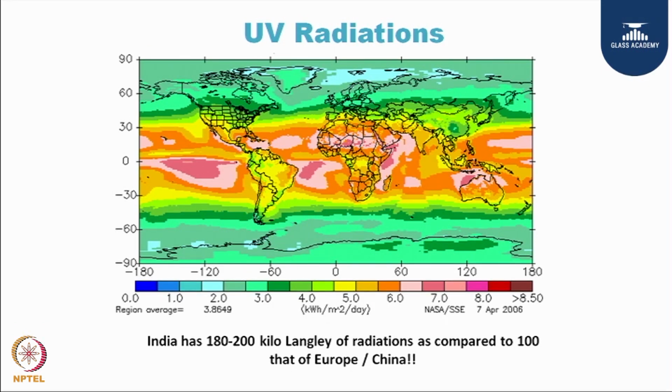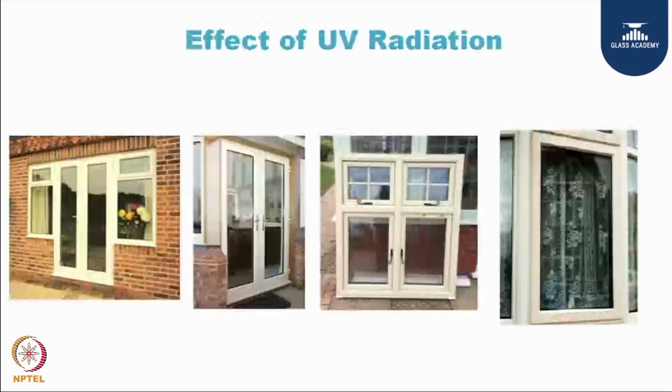Now, how you do that is by using titanium dioxide, as we discussed in the formulation part. And if it is not done, the initial way to figure it out is the yellowness of the window. Of course, there are many other reasons, but mostly with UV impact the first stage of degradation is the yellowing of the windows, and eventually it may disintegrate or break away as well.